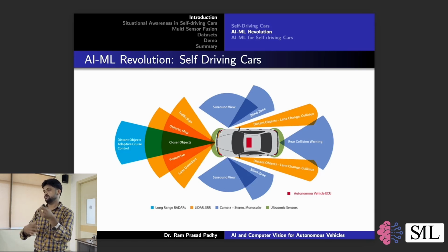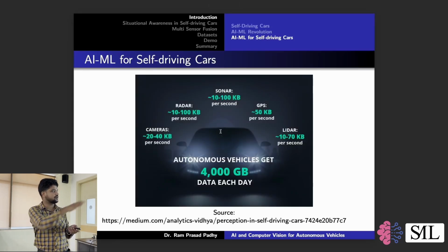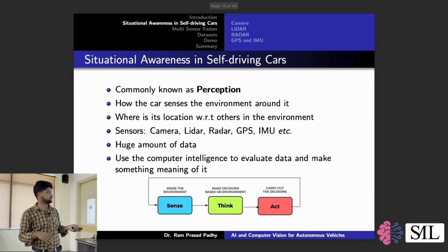If you find the velocity from other sensors like LiDAR and camera, it is not accurate, but with a radar sensor you get very accurate velocity. So generally we fuse all three sensors: LiDAR, camera and radar. The complexity becomes more, but the accuracy of information is much higher. All these things we are going to discuss in future slides.